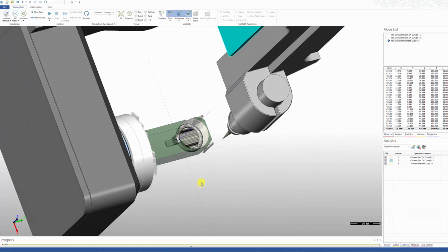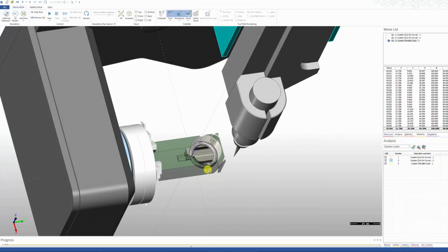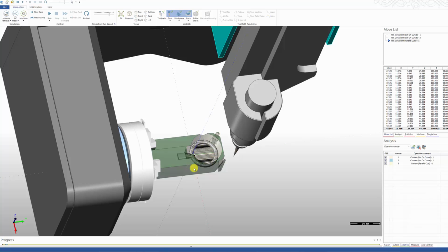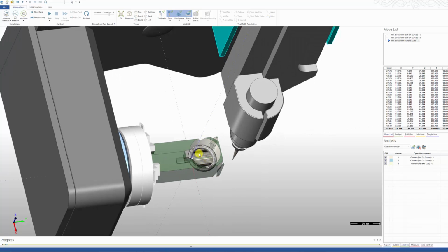This is both good and bad, depending on how you look at it. If you now do the opposite side, as we will do shortly, then essentially your ring is complete. You don't need to cut out the center part because it's already been milled out. The downside, of course, is that it takes a little bit longer to mill because you have all of this space to cut. So we will see that there's an alternative that will only cut this area, leaving the inside part alone.